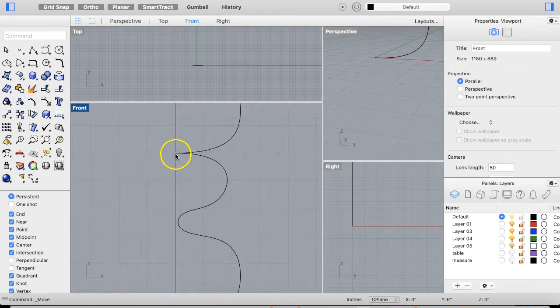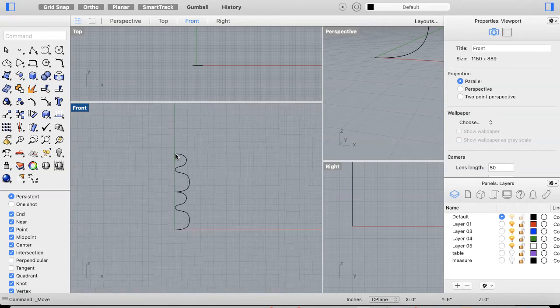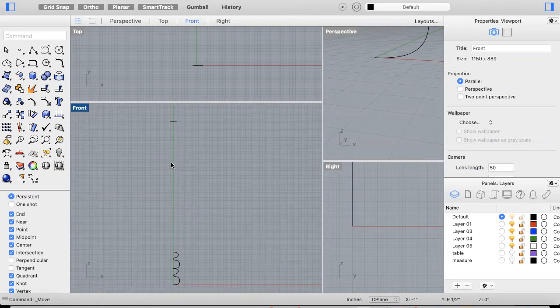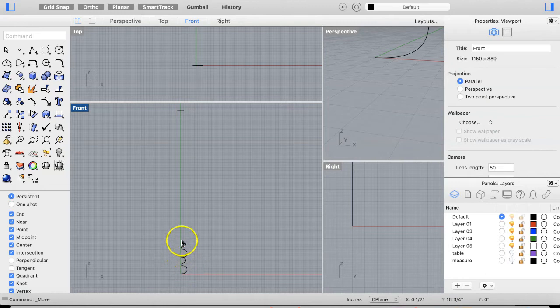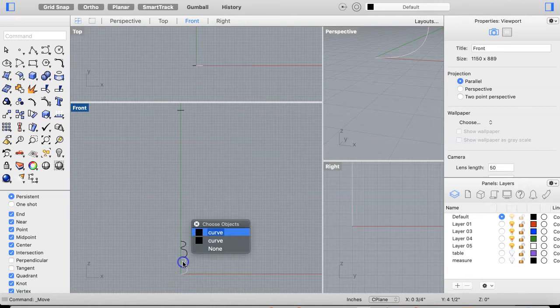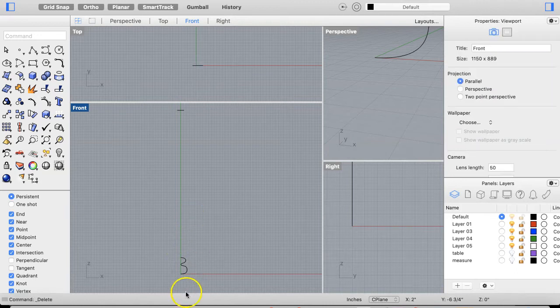So this way you can see here we have no overlap and the points are butting up against each other exactly. So I'm going to make sure that I have that piece up here. Okay, that's great. So that's going to be my limit for how many of these I make. And what I think I'm going to do, I may not use this second copy, but I'm going to take this first copy right here and do what's called a linear array.